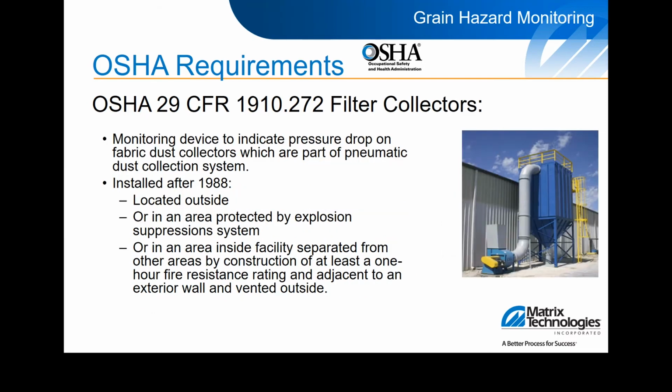Typically, most dust collection systems will have a differential pressure gauge on the unit for manual inspections. Newer dust collectors, and ones specifically used on larger multi-equipment systems, will include some measures and means of verifying pressure through control systems. These are typically interlocked to the control systems to allow equipment to run.